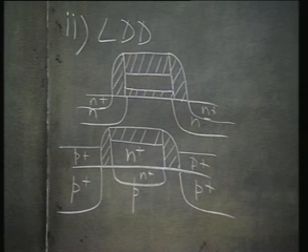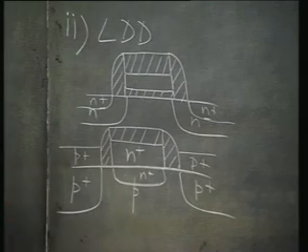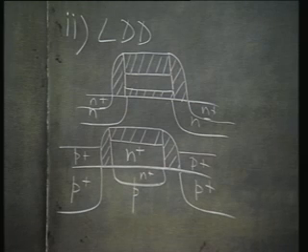The same kind of structure we are using both to realize a lightly doped drain as well as to self align the extrinsic base with the emitter. So, even this oxide deposition and the spacer formation can be done in a single step.